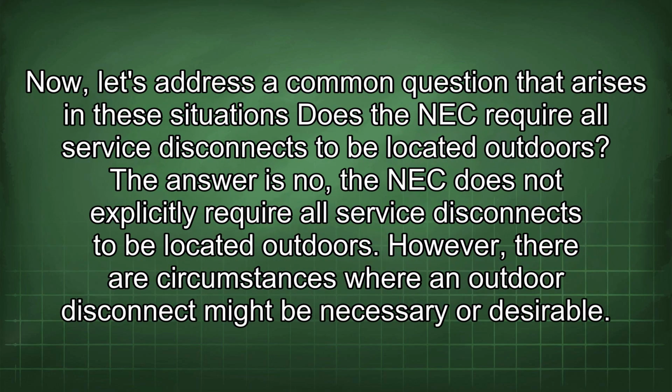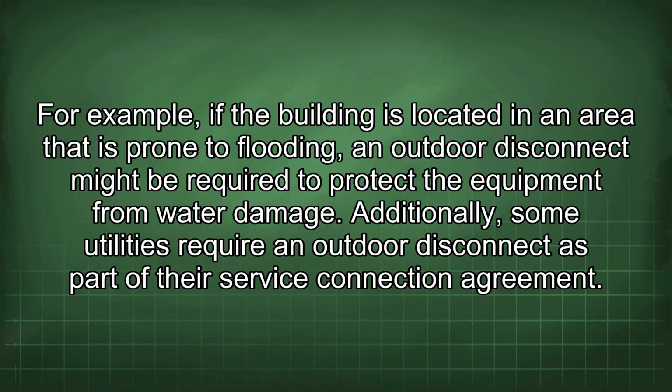Now, let's address a common question that arises in these situations. Does the NEC require all service disconnects to be located outdoors? The answer is no. The NEC does not explicitly require all service disconnects to be located outdoors. However, there are circumstances where an outdoor disconnect might be necessary or desirable. For example, if the building is located in an area that is prone to flooding, an outdoor disconnect might be required to protect the equipment from water damage. Additionally, some utilities require an outdoor disconnect as part of their service connection agreement.